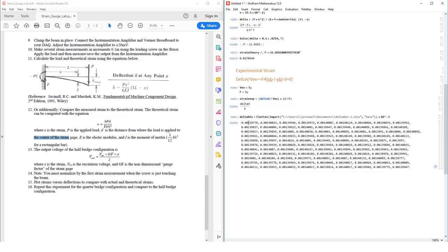So this is going to introduce some additional complications from just the theory that we've talked about. We're going to have to subtract from this. This is kind of like our baseline measurement. So without any deflection, we're reading this. So the delta V that we calculate for our deflections, we're going to have to subtract from this. I'll show you what that is in just a second. So I'm going to copy this. Instead, I'm going to do 0.1 inches, and I'm going to pull in a data point from here.